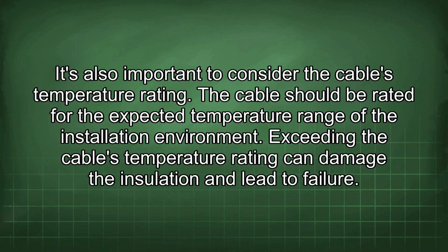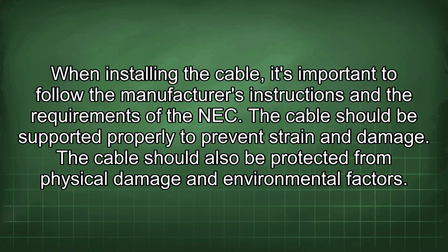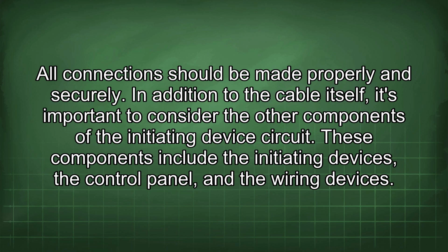It's also important to consider the cable's temperature rating. The cable should be rated for the expected temperature range of the installation environment. Exceeding the cable's temperature rating can damage the insulation and lead to failure. When installing the cable, it's important to follow the manufacturer's instructions and the requirements of the NEC. The cable should be supported properly to prevent strain and damage. The cable should also be protected from physical damage and environmental factors. All connections should be made properly and securely.